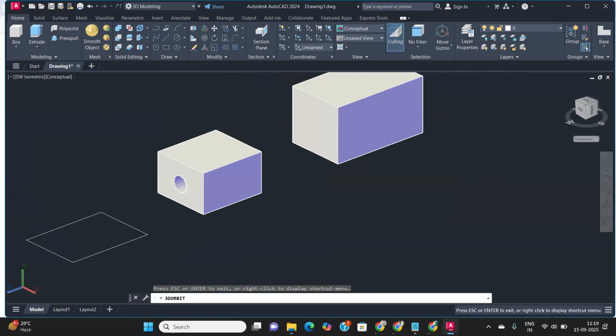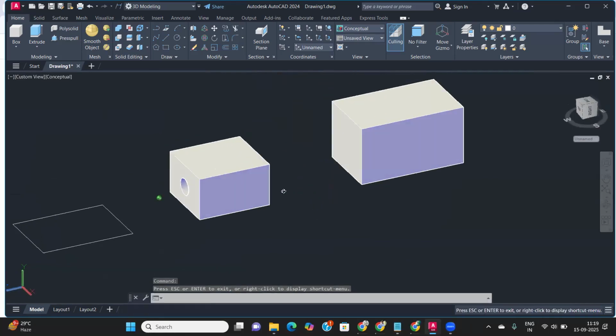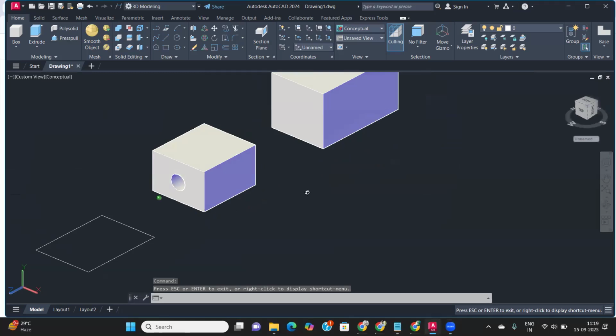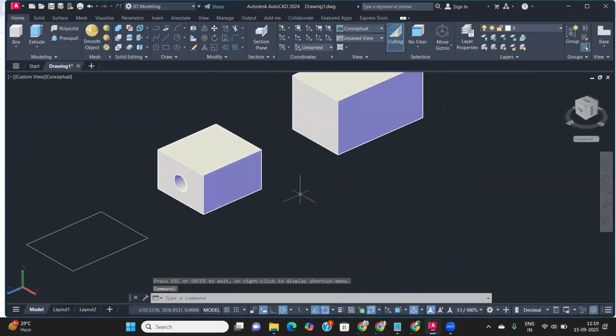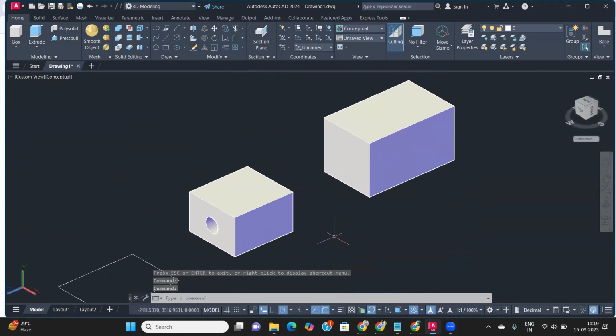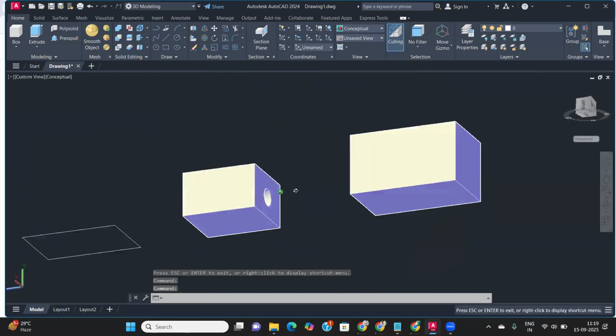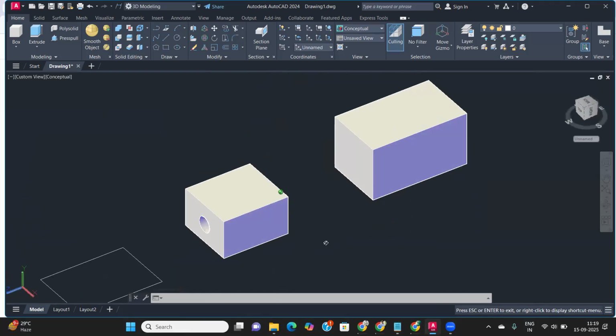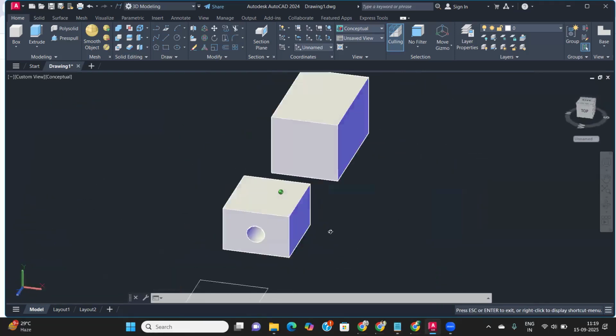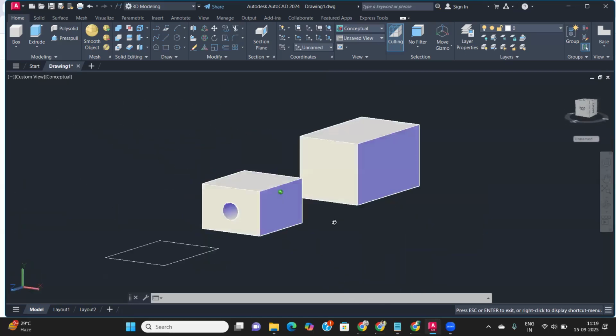What is the shortcut? We hold the shift, and then press the mouse middle button, okay, the scroll middle button, then just rotate it where you want to scroll and then pan it. Just use shift with the pan button. Then what you get here, you can scroll it and show anywhere. Okay. If you want to scroll and show it in orbit mode. Okay, if you want to show any edges right here, then you can use this.